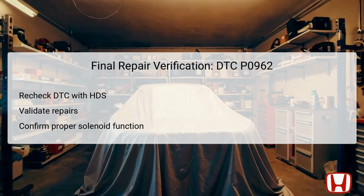Validate that all the connections and wiring are secure and that the solenoid operates correctly. It is critical that the entire system functions without triggering any further diagnostic trouble codes. A thorough verification confirms the integrity of the repairs and ensures optimal functionality of the CVT specific to the vehicle's performance.